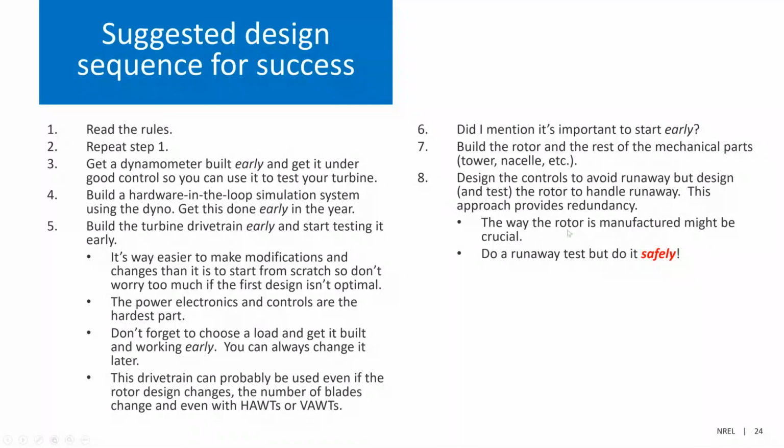The way the rotor is manufactured might be crucial. Think about that, especially if you're using 3D printing to build your rotor. And make sure you do that runaway test, but think critically about how you're going to do this, because those blades could end up going really, really fast, and they could end up breaking, which means do it safely. Don't be in the rotor plane or anywhere near it, and do it as though it's going to explode, and be safe in that case.